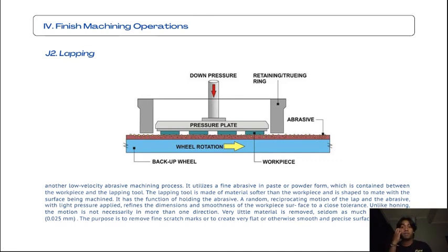The operation can be performed by hand or with a machine designed for the purpose. In some cases, abrasive coated paper, bonded abrasive, or cloth clamps are used. The relative motion between the lap and the workpiece is always low. Typical applications are finishing of gauge blocks, plug gauges, ball bearing races, valve seats, roller bearings, and optical parts. Parts requiring metal-to-metal sealing surfaces are frequently lapped.